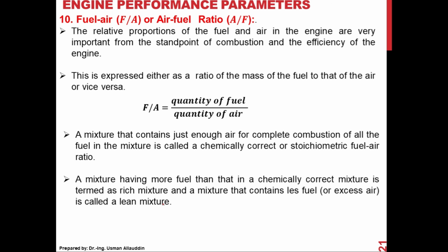So it is always best practice to run the engine at either a stoichiometric fuel air ratio or a lean fuel air ratio. Fuel lean means oxygen is in excess. If oxygen is more, then it will make sure that all the fuel will be burned in every case.